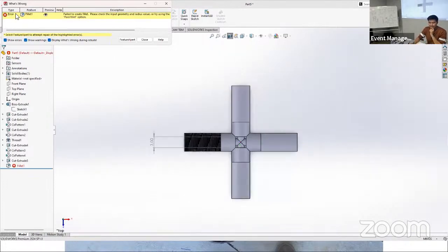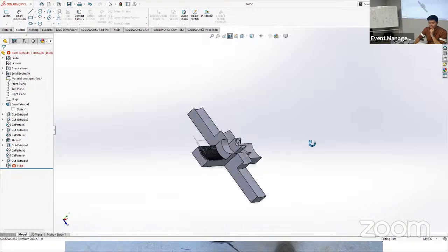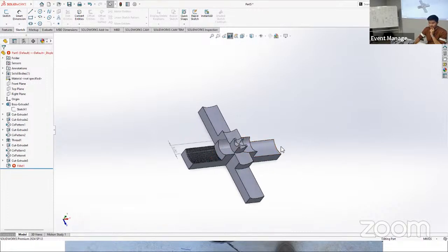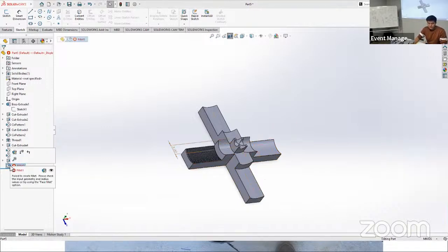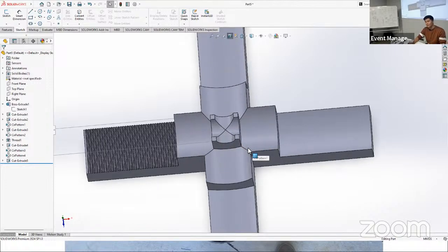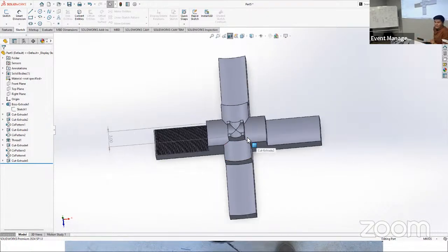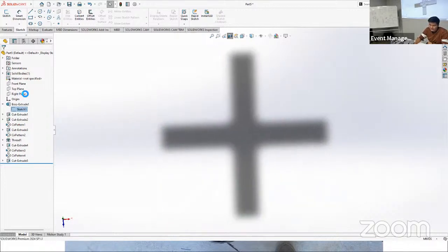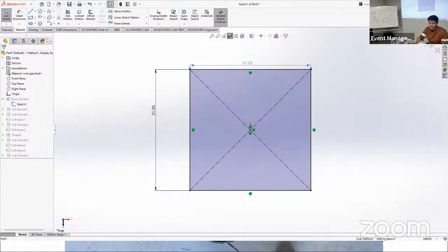Okay, so as you can see, there's an error, but the error is in the fillet. So our last step, it actually makes it like that. Oh my. So if we just delete the fillet, we end up having that figure, and it's very close. Oh, so there's the mistake that we made, or more particularly what I did. Our goal was to go from a 12 millimeter gap to a 9 millimeter gap, which will take 3 millimeters, 1.5 from each side, not 9. So we should redo our shape into 37 millimeters.